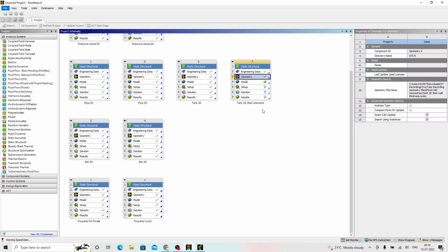Now we are going to extract just the mid surface of this entire tank. One thing we are sure about this tank is it has a uniform thickness across, because that might have been done with a complete solid model and with all the cutouts at the periphery. Then a designer must have used a shell command to make the inside surfaces hollow to obtain the uniform wall thickness for the entire body.